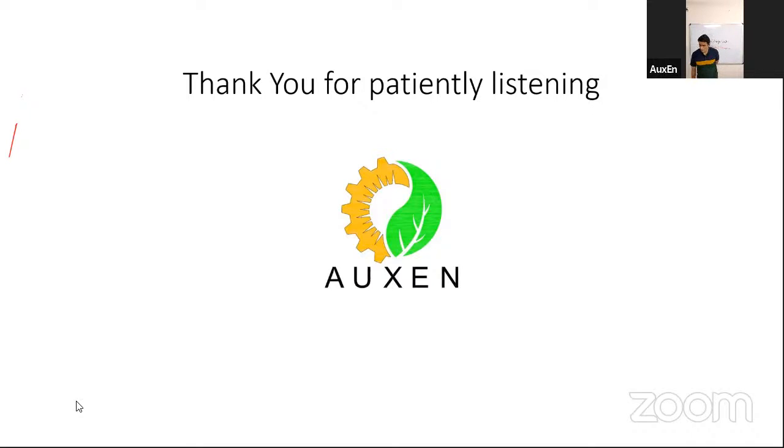Yes, Mr. Vasant is asking about a practical difficulty that he has faced. He is asking what is to be done when we come across a situation where a column on the ground floor is slightly displaced from its normal position, but the columns above are in the same position. So I think you are talking about transfer columns or planted columns, a situation where your columns are not in a vertical line and some columns are shifted to accommodate some utilities at the lower levels. Maybe not in the project that we take up, but I will try to cover this issue separately, because it requires some understanding of other issues involved.